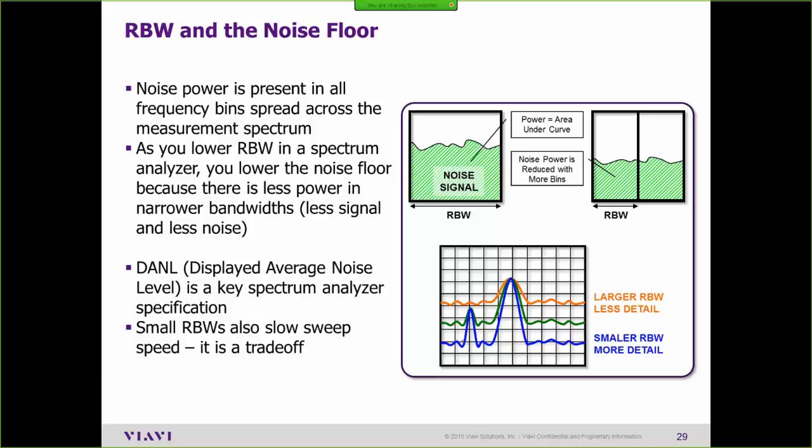All the different technologies out there have a noise floor, and if you look at this chart, it turns out that in a 1 hertz bandwidth there is -174 dBm of noise. It's always there. You can't get rid of it no matter what. So when you talk about different communication schemes, they operate in particular bandwidths, and they have certain amounts of noise that are always present in those bandwidths.